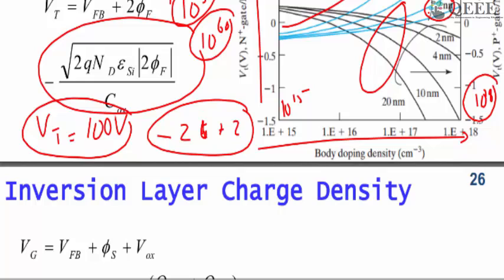So threshold voltage is nothing but, it's like you are putting some number. You are calling it that the transistor is on beyond threshold and off below threshold, but we will see later that the current does not go to zero, because it's a continuous process. That is why you might have heard about something known as subthreshold current. We will see later that there's a small subthreshold current, but the subthreshold current is not there in a MOS capacitor because there is no source or drain.